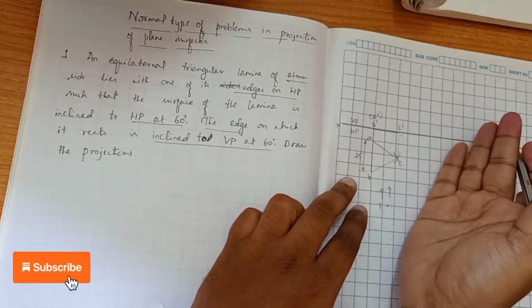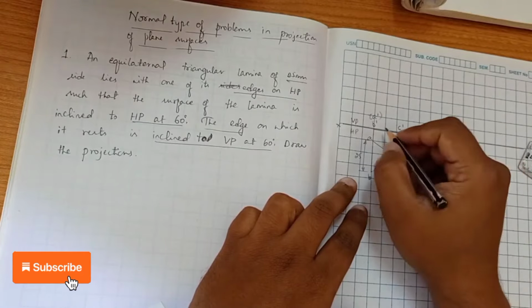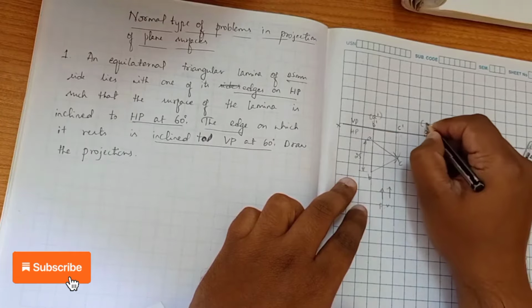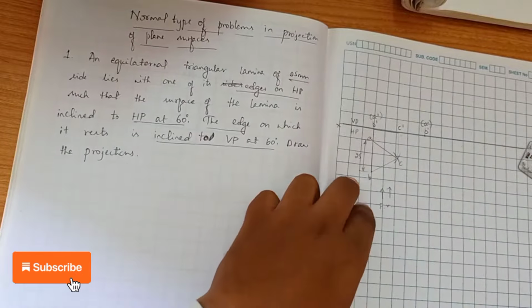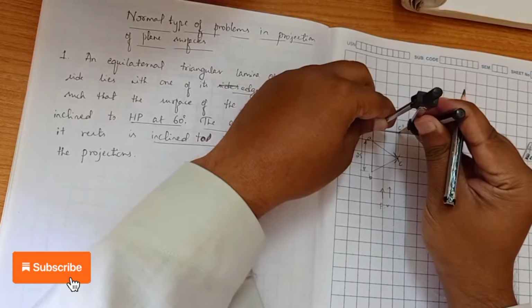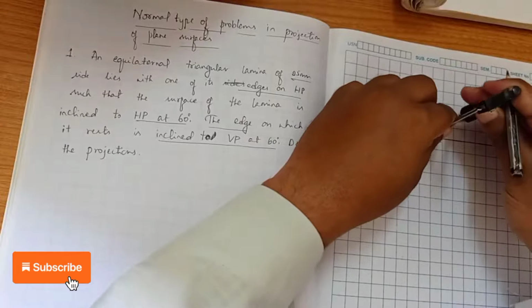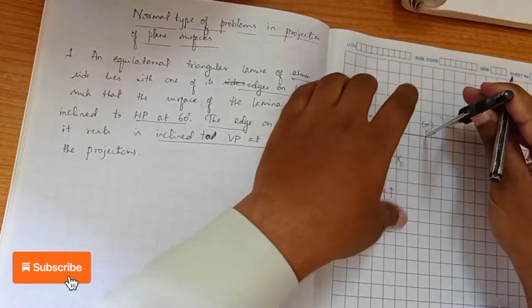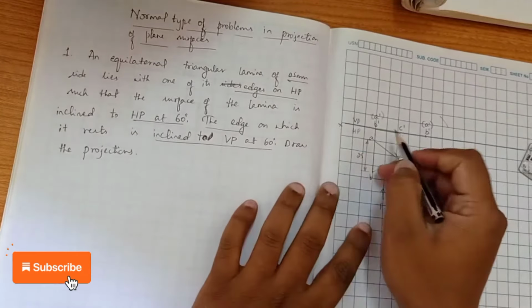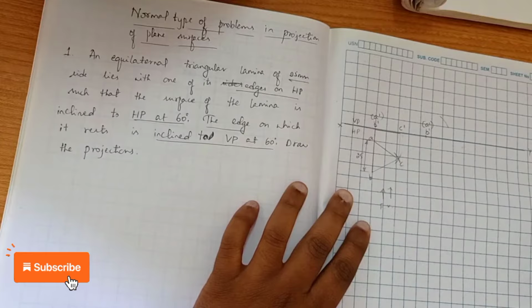Okay, I'm going to show the first front view, then I will draw the inclined top view. For that purpose, first I will be writing this B dash and A dash. This is our reference point. After that I'll be measuring this length, that is B dash C dash, and cutting the arc. Now we have already cut the arc, but we know that we have to incline this B dash C dash by an angle of 60 degree.